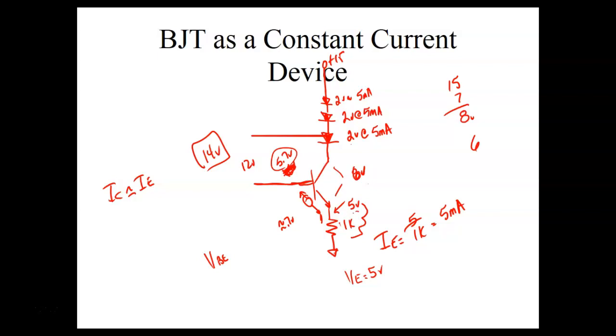So that's why light bulbs are rated at a voltage. And they rate them at 115 volts, even though NEC says the nominal voltage is 120. So most of your loads, even though they're rated at a certain voltage or power, those are not exactly precise. So usually, whichever one you design around, either 12 volts on your car or 115 volts or 14 volts, you're okay.